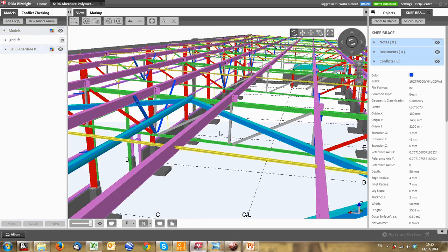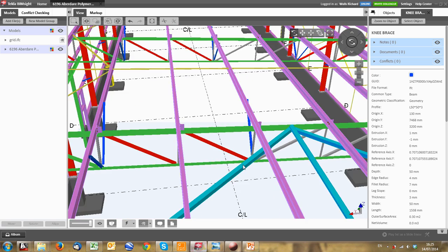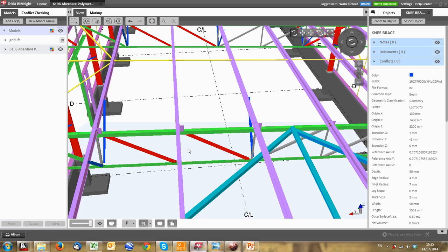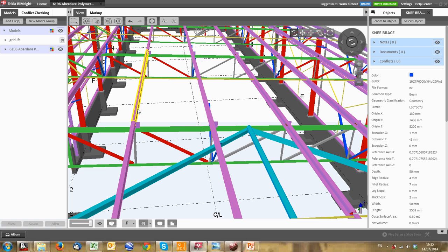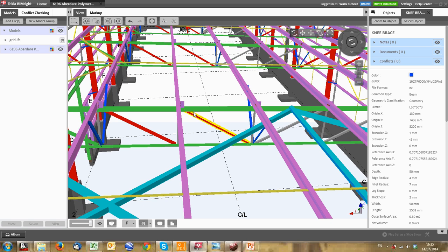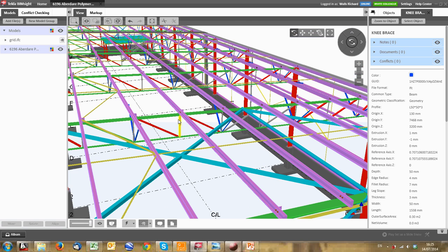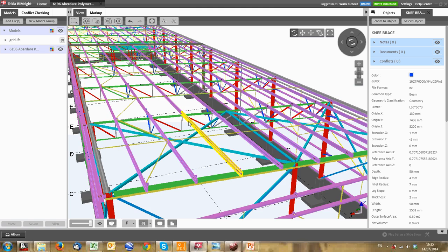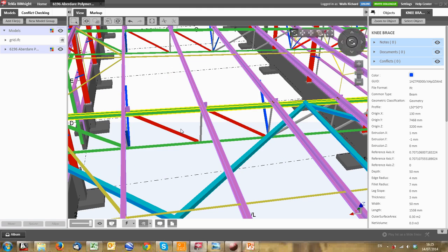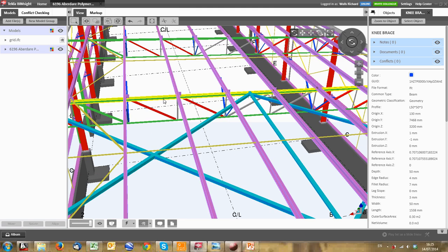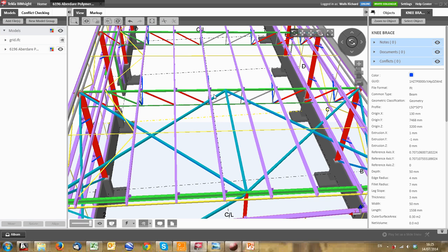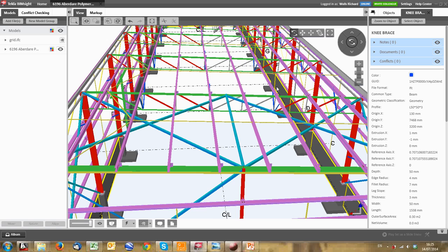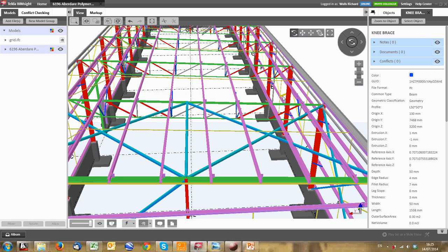They're always on top of the truss structure. That's because the load then doesn't create any bending in this top chord of the truss. So you always put your purlins directly on top of your truss there and the truss nodes. There are ways you can put it not on a node, but then you just need to make sure that this member is designed to carry that. So we're now going to start setting out where all these purlins are all the way down, so we can screw our sheeting to that.